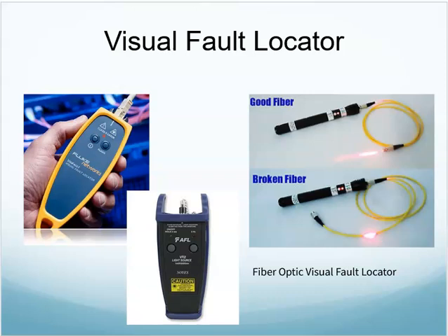Sometimes, with terminating fiber or splicing fiber, you run the visual fault locator through, and as you're mechanical splicing, that's the one I was trying to think of. When you bring those two fibers together to mechanically splice them, if light comes out the other end of the fiber you're hooking into, then I know I have those mated well, and I can quick attach that mechanical fastener to hold the splice together.